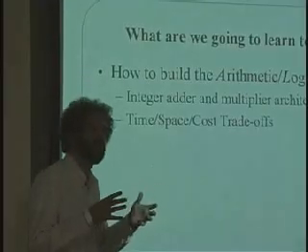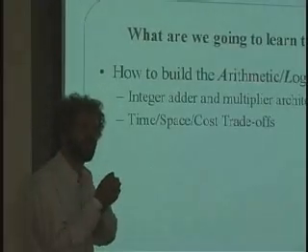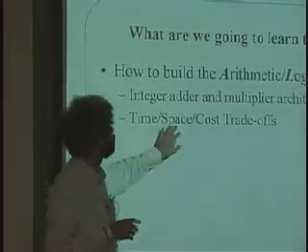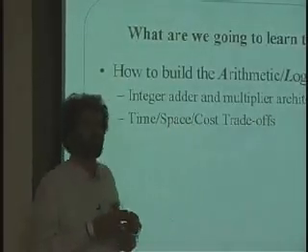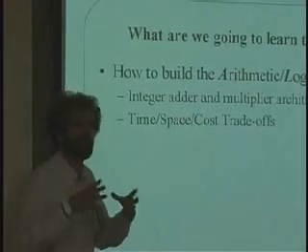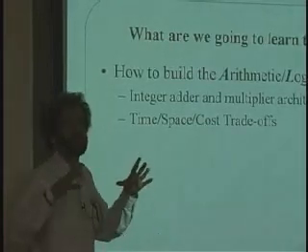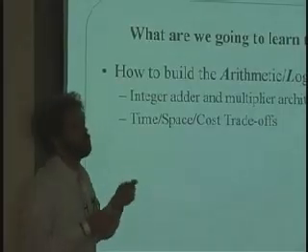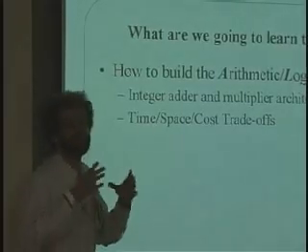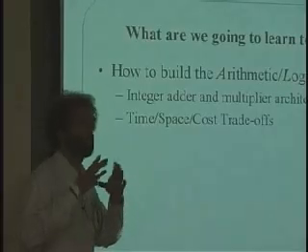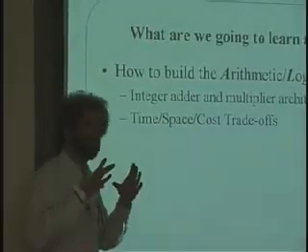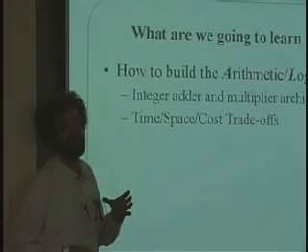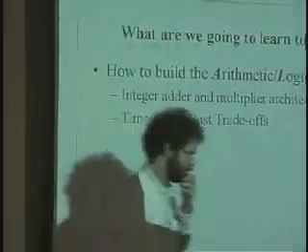Okay, in general, it'll be possible to make an ALU that's very small but very slow, or very big and fast. And of course, space has a lot to do with cost, because the larger the ALU takes up the area of the chip, the bigger you have to make the chip, and thus the more it costs. And the reason is not that the bare materials cost very much, but the bigger the chip is, the less likely it is that everything on the chip will be perfect, and thus the yield of how many chips are good goes down, and thus the cost goes up.